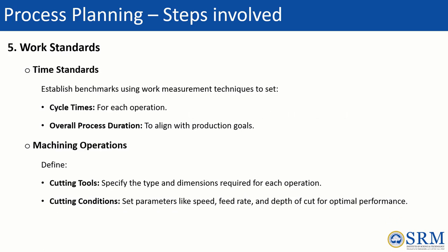Coming to the work standards, they establish the performance benchmarks. Time standards are developed to determine cycle times for individual operations and the total production time. In machining operations, appropriate cutting tools and cutting parameters such as speed, feed and depth of cut are selected to achieve optimum productivity and quality.